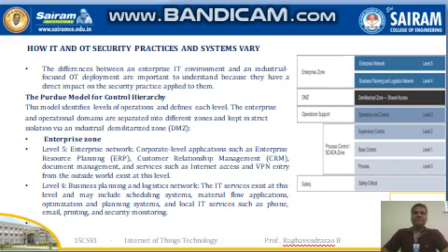The next level is level 2, that is supervisory control. This level includes the zone control rules, controller status, control system network or application administration, and other control related applications such as HMI, that is human machine interface, and historian. Basically these things are kept for the supervisory model. In one particular location, everything can be visualized, and based on that, the actions are taken.